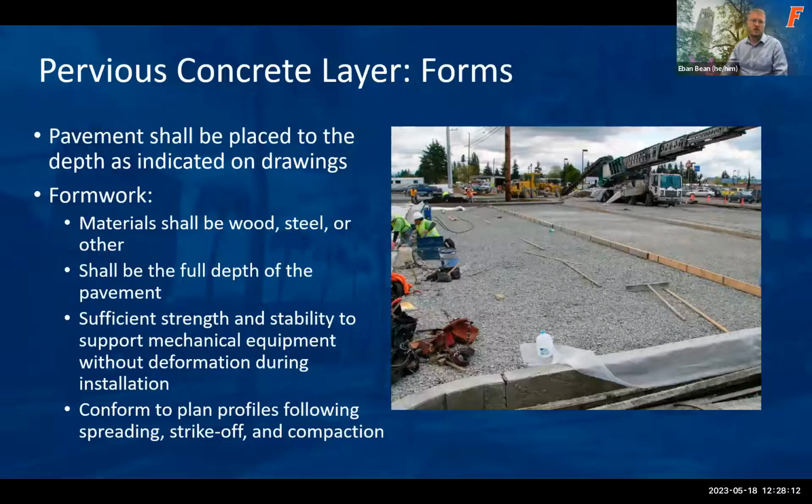With the installation, you want to make sure you have either wooden or concrete forms that are rigid enough so that when you put it in and when you're driving over it, they're not flexing and deforming. So it's really important to do that.